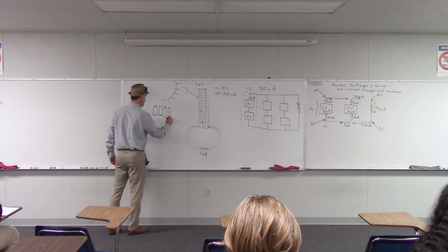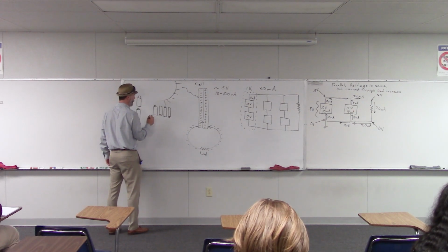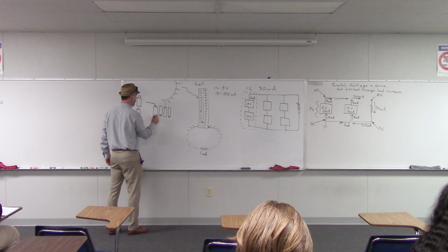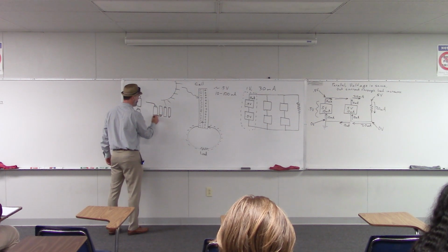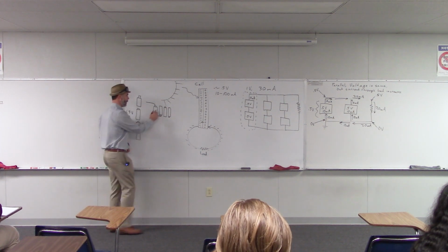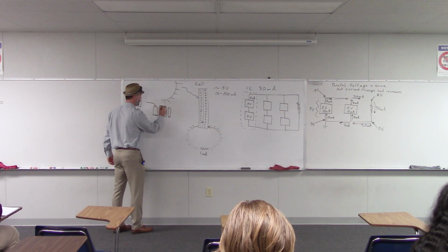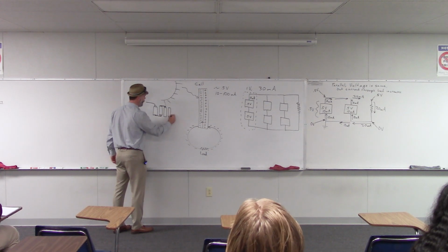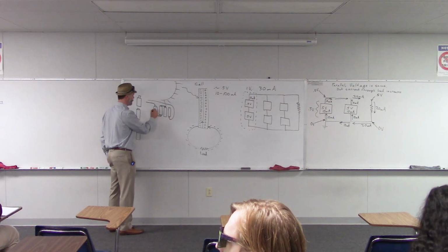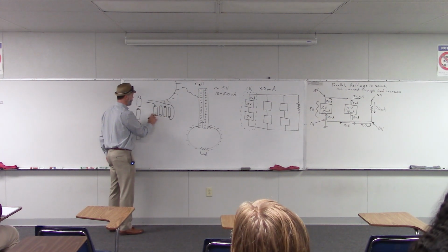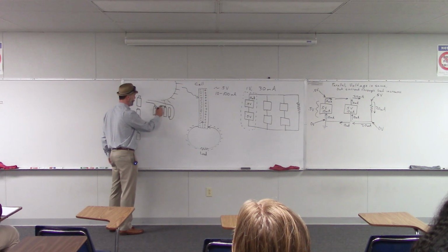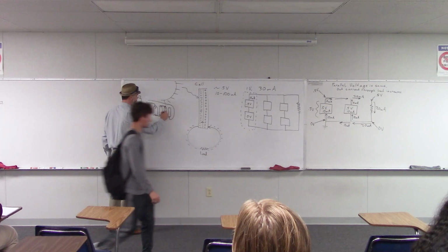So if you look closely, normally what you'll see is there'll be one wire coming out here, and then there will be a little metal connector between those 2 terminals, and a little metal connector between those 2 terminals, and then the other wire will come out over there. So what you've really done is you put these batteries together in series. You've connected the negative end of one battery to the positive end of the next, and so on.